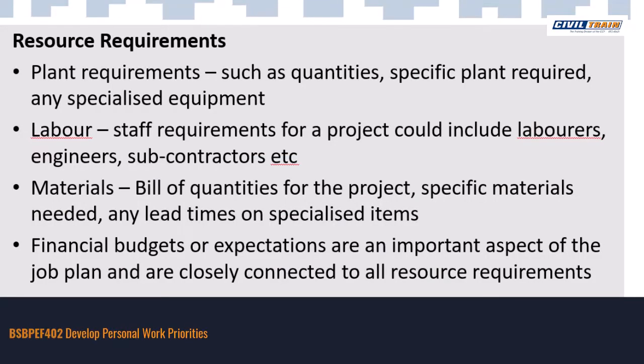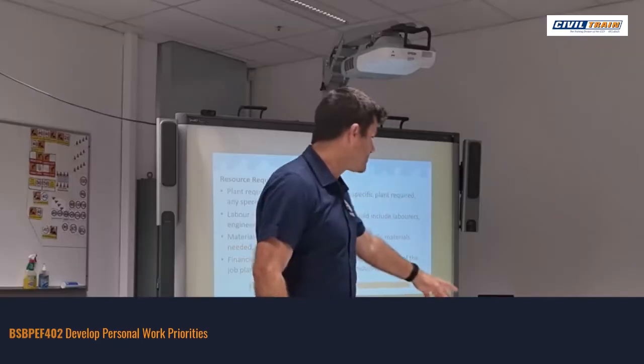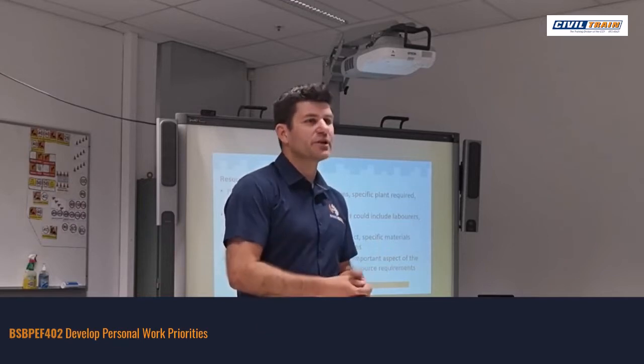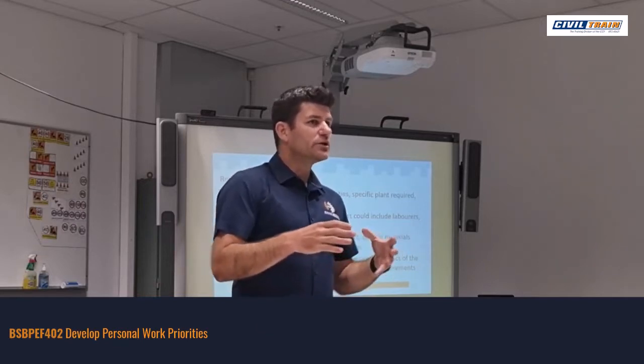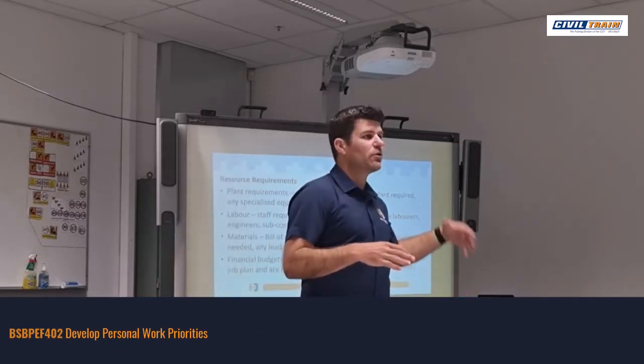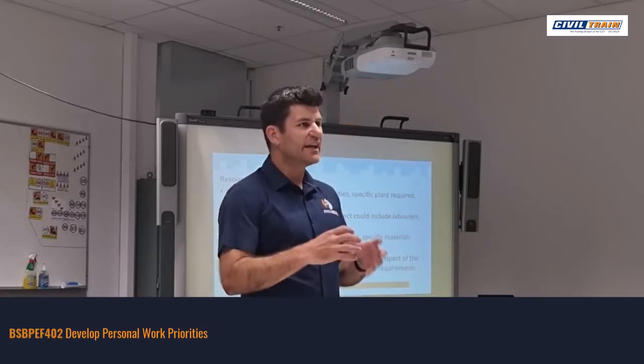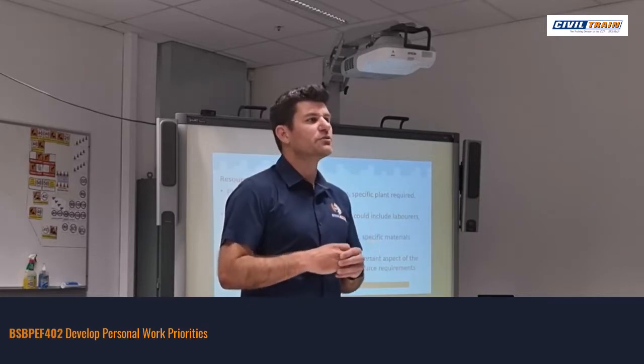Materials, bill of quantities for the project, specific materials needed, any lead times and specified items. So with this particular project, I'm not going to get you guys to write a full bill of materials using specifications, but what I would like you guys to do is identify key materials in the fact of a delivery for your schedule. So if we're talking about that we've got concrete or pipes that are going to be laid, or we've got key resources, I would like to know in your schedule when those resources arrive.